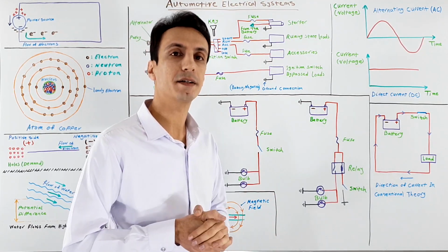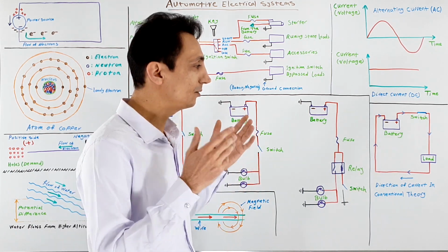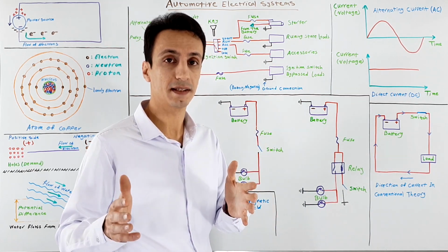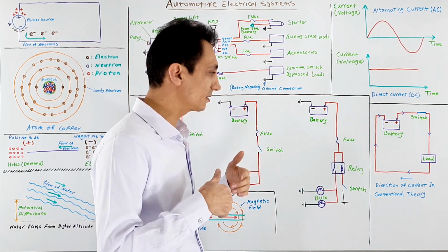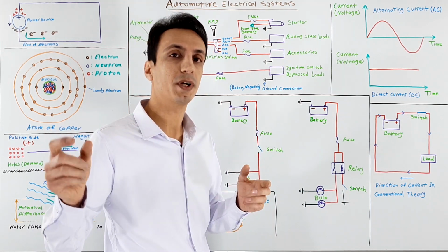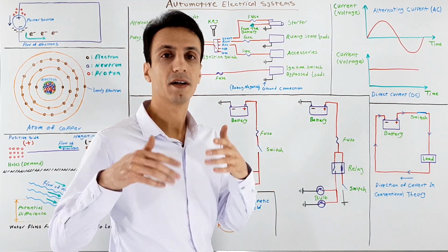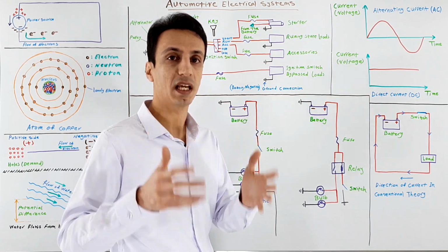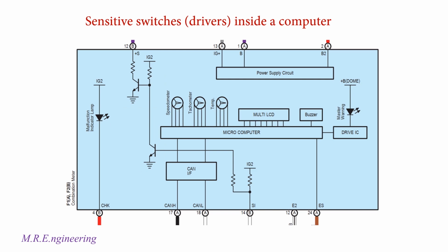Components that demand high currents require larger diameter wires in their circuits, but you cannot use these high current wires in a circuit that a switch is controlling in series. The reason is very simple. It's because the cost of routing these larger diameter wires to the switch and then to the consumers increases, and also the sparks and arcing that these high currents make when the switch opens and closes will damage the contact points of that switch. And remember that many of these switches are located inside the sensitive ECUs.